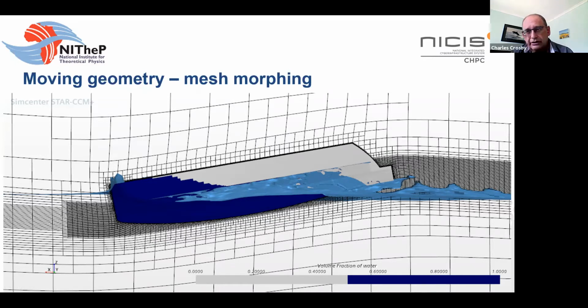This solution was not intended to happen. This is a boat, a power boat, and I applied the thrust line wrong in setting up the calculation. And effectively, the thrust line was up here instead of being down here somewhere, where normally with a boat, you put the propeller underwater, not in the air. So in this case, it thought the propeller was up in the air. So it forced the boat to nosedive. And I was rather expecting the whole solution to break when it got to this kind of pitching angle, which is about 10 degrees or so. But the method was sufficiently robust, actually, to not fold up the mesh before it got to this point. A little bit after it got to this point, some grid cell somewhere folded over itself. You get a negative volume and the whole thing blows up.